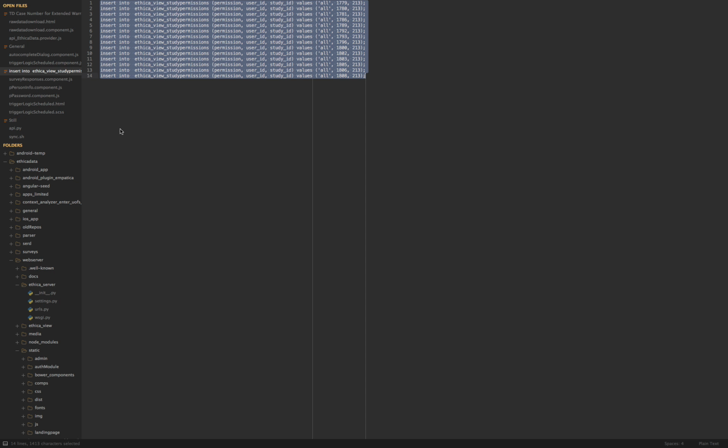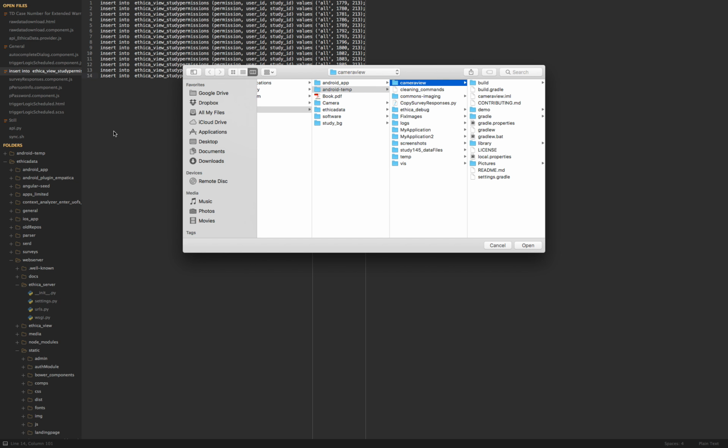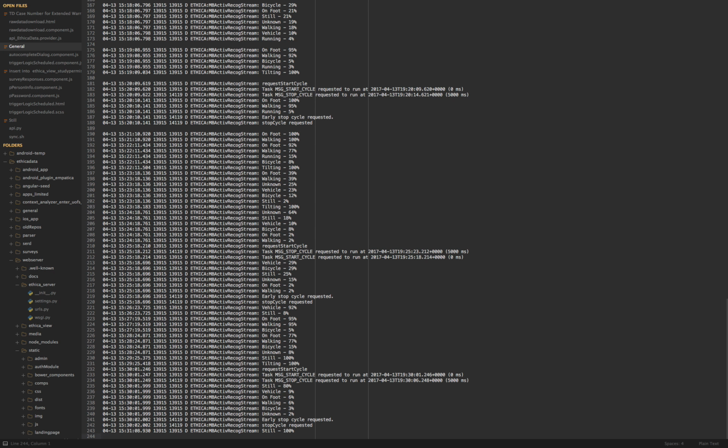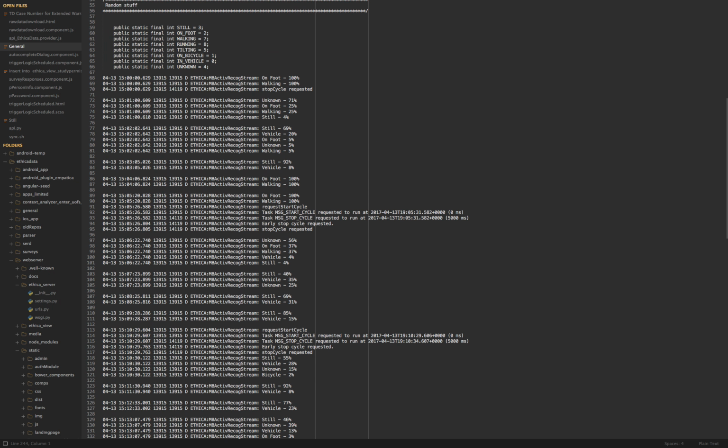Do you get that data from the hardware? We get the hardware data, then we do one level of processing on top of that. The hardware is accelerometer, gyroscope, and magnetometer. You do one level of processing on top of that and get linear acceleration and device orientation. Based on those two, you do one more level of processing, and then you get the number of steps taken and the type of activity.